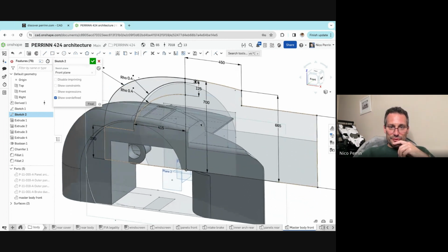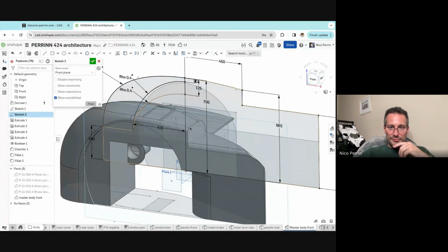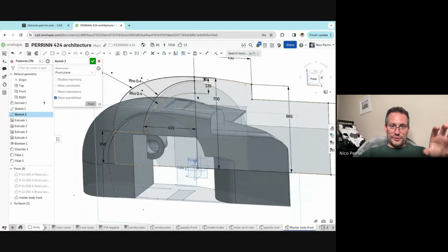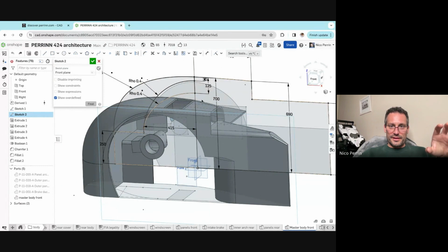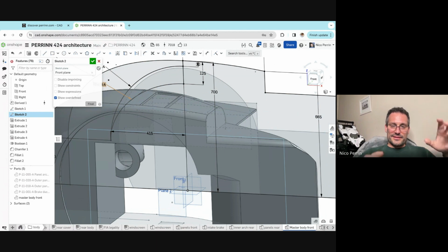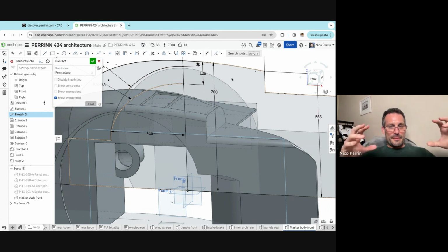There's going to be some issues there, I can tell, in terms of the fillet is not going to work. But anyway, you can see how the shape has automatically been affected. If I come back one step, you can see the opening changing at the back of the front wheel. That's typically a test I would do in aerodynamics. I would do that sort of 25 mil change. I would expect by closing the exits behind the front wheel.